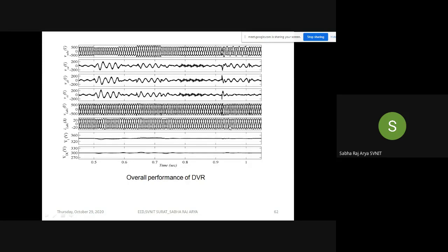is to see how much time it is going to take to recover the DC link, and how much time the device is going to take to settle the value of load voltage. So we need a response within half a cycle or maybe less than that. That response time we should also record. At the same time we can see the condition of the PCC DC bus voltage, how the DC bus is going to vary, and the value of terminal voltage.